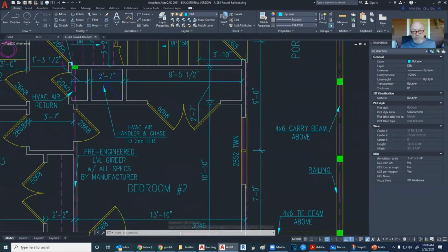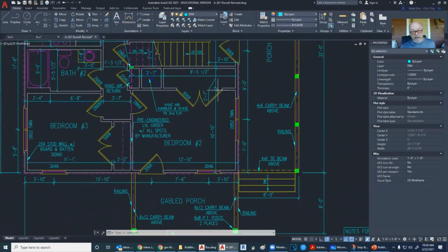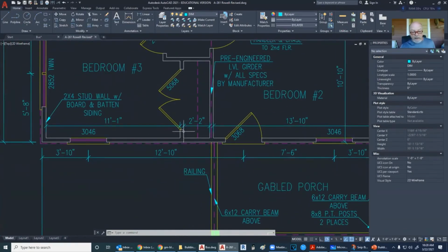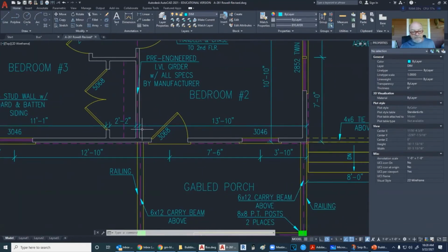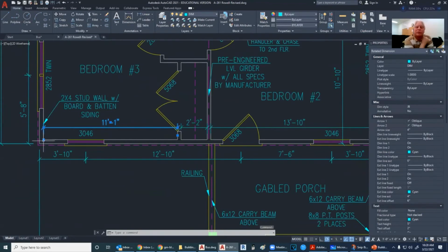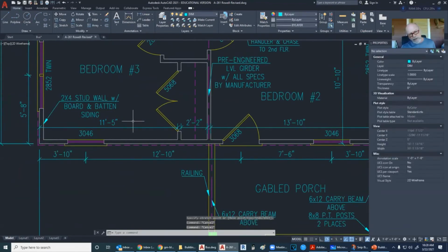And this is not including any kind of finish on it whatsoever, because when the framer gets in there, he's got a 2x4 in his hand, and so that's the dimensions that are going to be for him. Well, you almost have to dimension to the center for a frame or it won't come out right. What do you mean? Center of what? The center of the stud.